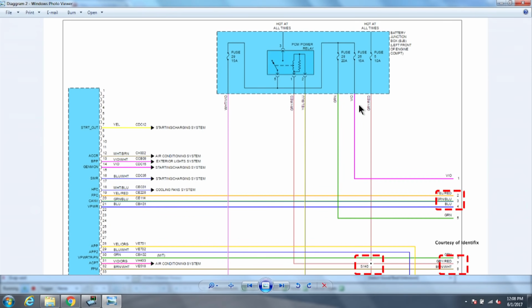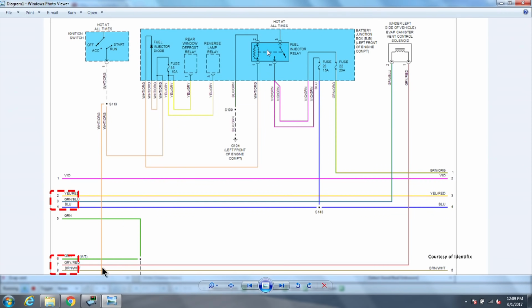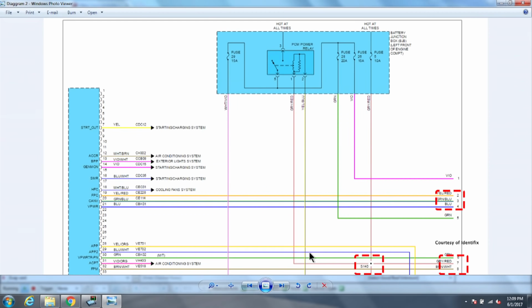This is our power supply that's supposed to come from our relay. Goes to splice 140. Comes from our relay, right? So if we turn our relay on, we should see power here. But what is this? Fuse 5, 10 amp, hot at all times, feeding down to splice 140, through pin 7, down here, up to our vent solenoid, through pin 1, through the solenoid, because we have an open circuit in our PCM right now, through the solenoid, back through pin 2, back through green and blue, and back to our back probe right now, 12 volts.